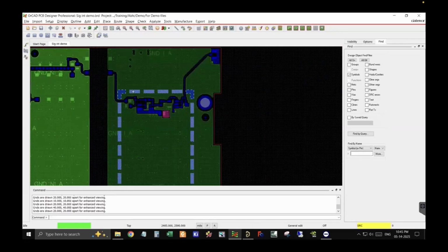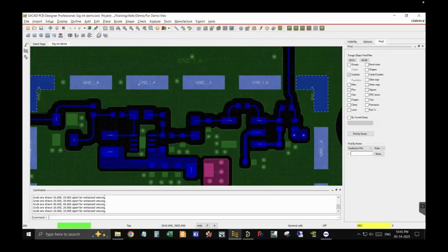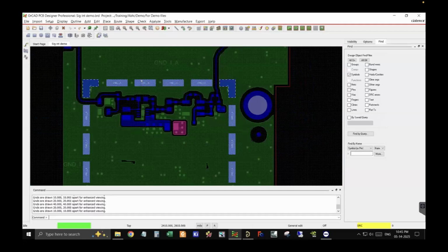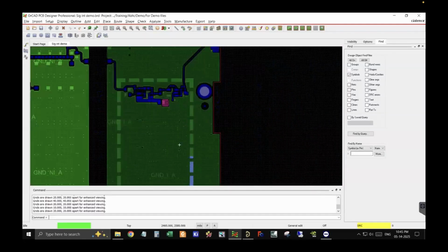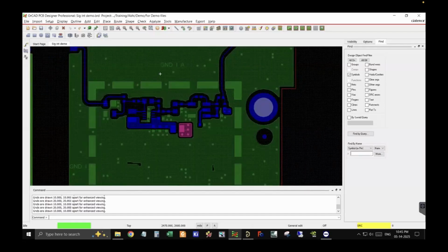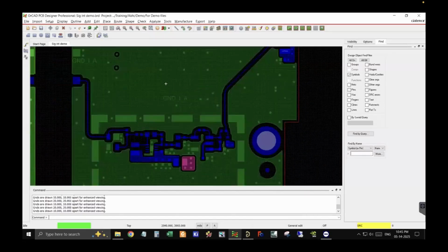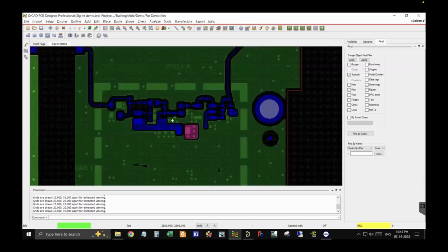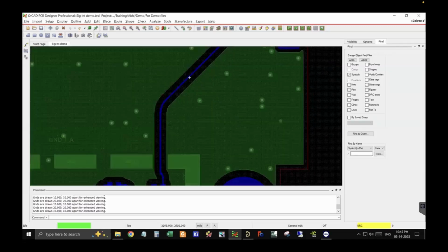Now I'll just show you. Before that, we have also used a shield over here. As you can see, the one which I am highlighting, it is a physical shield which is put around the circuit. So whatever EMI radiations that is occurring over here, we make sure that it is not interfering with anything else outside. The noise is not interfering with this particular circuit because it involves a lot of high frequency signals. So I'll just show you.